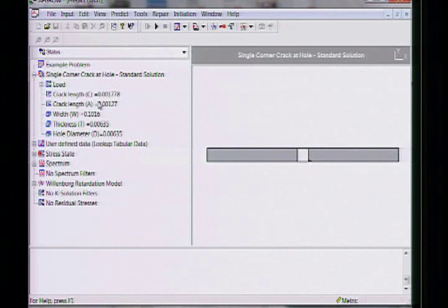Meters? Meters. Now people ask sometimes, why don't you use millimeters? Because a lot of people, when they do crack growth in the metric system, they will use millimeters because it's more suited towards these 0.5-inch flaws. And then we don't, because we try to be consistent with our SI units, because sometimes when you convert from one to another, if you do your crack length in millimeters, you do something else in meters, you're asking for trouble. We keep everything consistent.